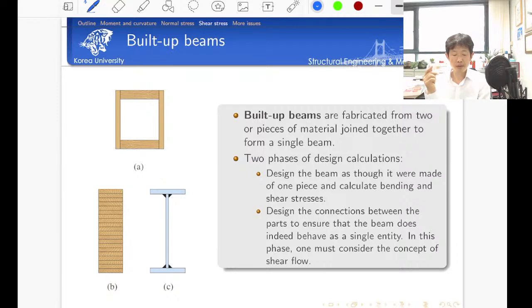So in most cases, materials do not tend to fail by the shear stress. Usually the materials would fail earlier by the tensile strength, typically. But of course, in the case of high ductility steel, the shear deformation is much more important than the elongation in the longitudinal direction. But let's consider the built-up sections here.